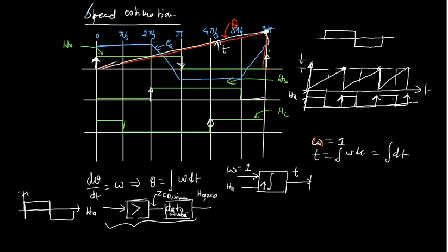So what we do is use a sample and hold arrangement. These blocks are there. Up till where does it have to hold? It will hold from rising edge to rising edge. So take the same Hall sensor signal and give it here to get that same Hall rising edge. So the value you will be getting is your time period.